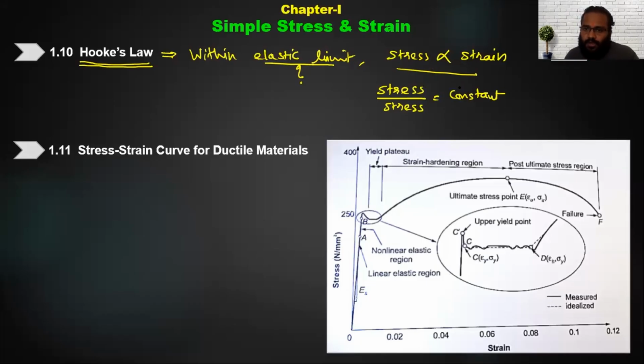We will be studying that in detail. That constant is also known as modulus of elasticity. Stress upon strain, that is modulus of elasticity. As you can see, this modulus of elasticity will have the same unit as that of stress, because the strain has no unit.